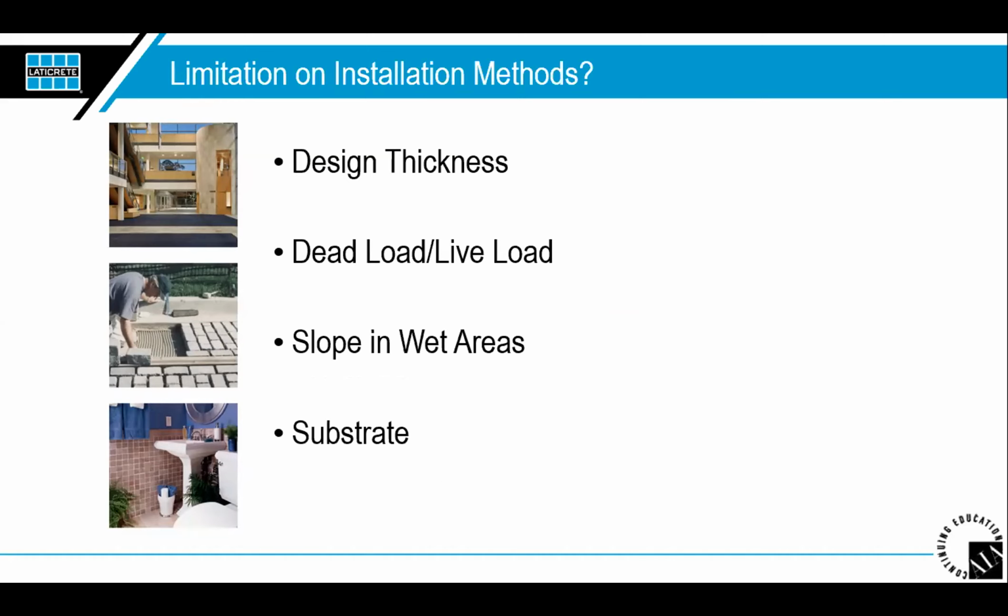Sometimes when we get in there with the tile or stone installation, the walls are already set and the doors are already there as well, and then we find out that we're 1/4 inch too high, or 3/4 of an inch too high. It can really vary in different scenarios, but it is a big deal. So thickness is an important consideration, right? Like I said, door heights, dead load allowance. How about ungauged or gauged tile and stone? The ungauged can have different thicknesses. That's a big deal when you're talking about slate installation, for example. Slope to evacuate water, if necessary. All these have to be taken into account.